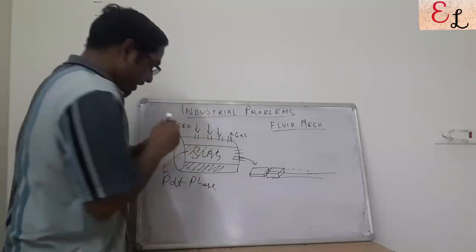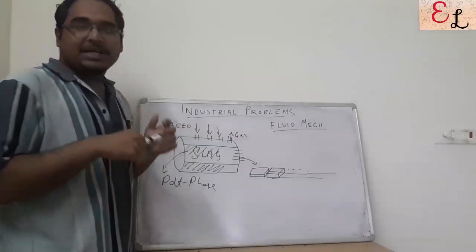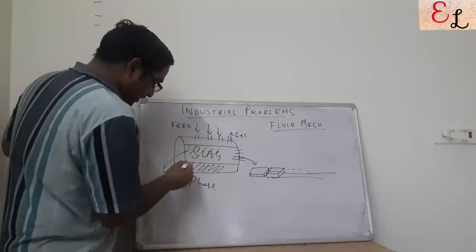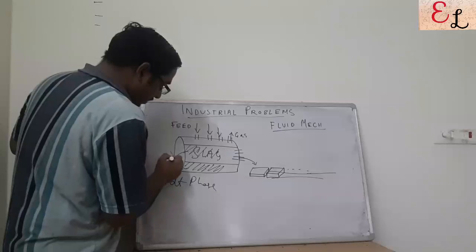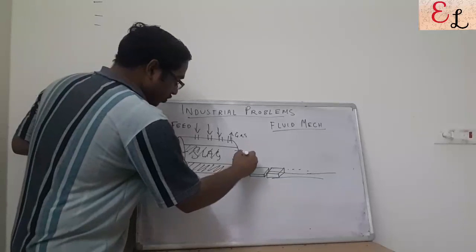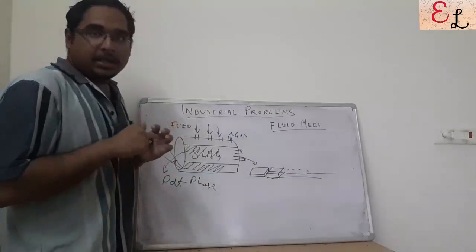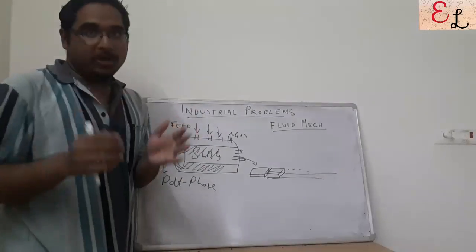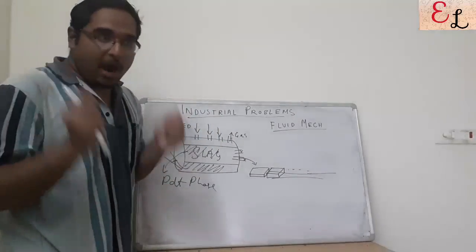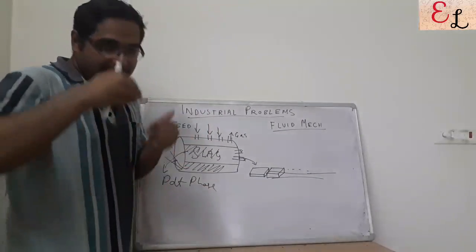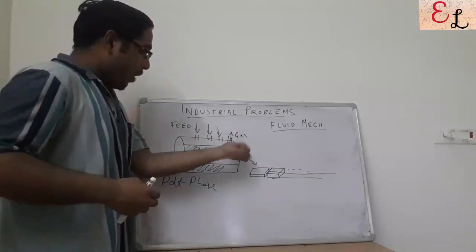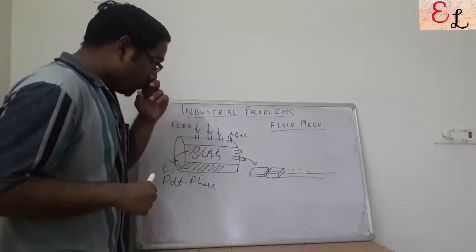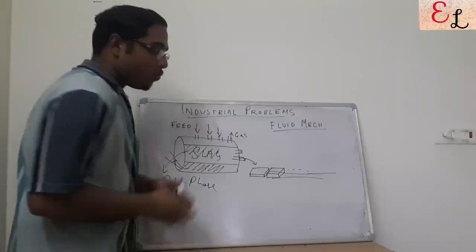It's a liquid phase, and it's a semi-batch process wherein these holes are closed. There is one siphon here, one hole here to tap out the lead. This is also closed, this is also closed. All the three outgoing points are closed, the inlet points are open. So inlet is continuous, whereas outlet is done in batches: after approximately 2 hour intervals, the outlets are opened. So what was the problem as the slag hole was opened?